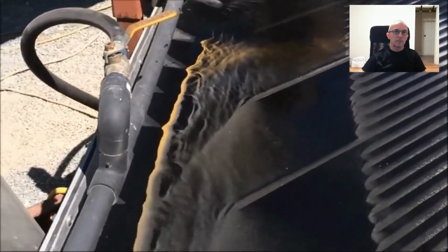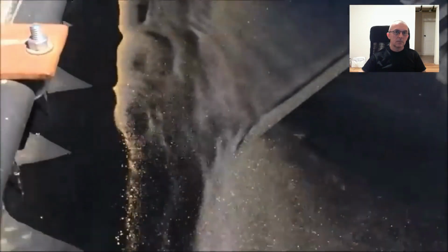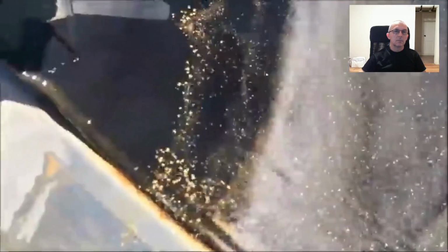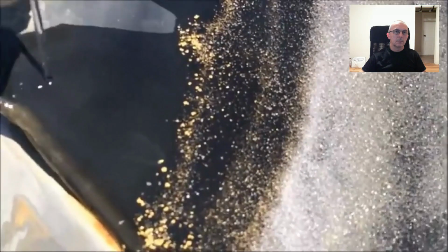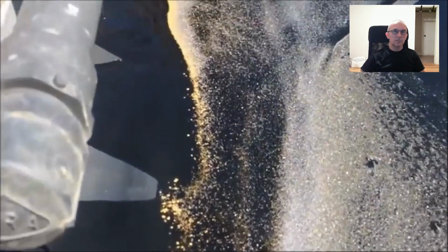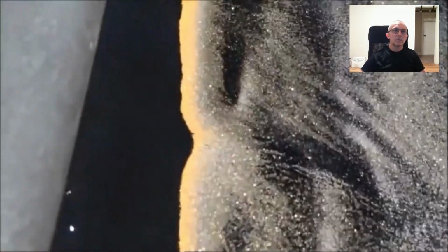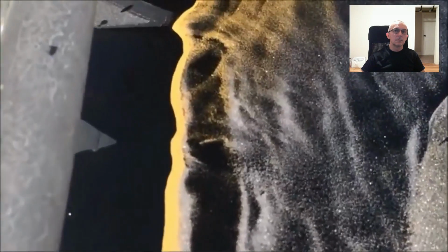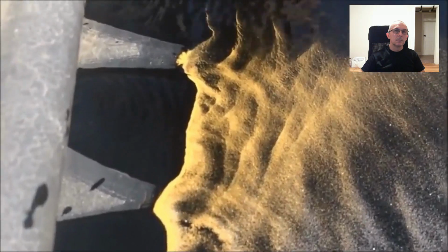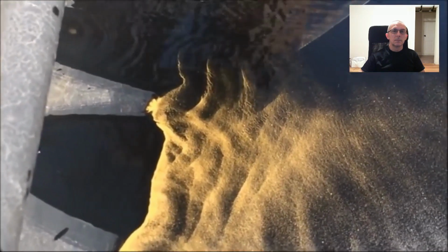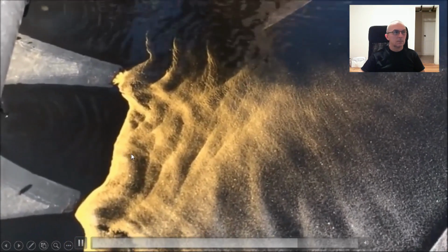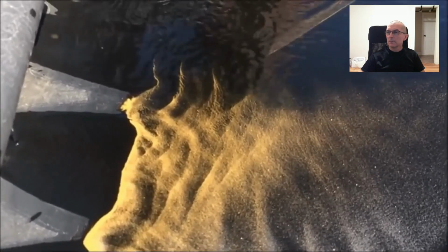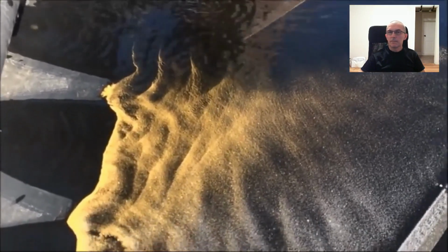The good part of this is just smoke on the table. The big pieces have come down already. They're already down here. These are the bigger pieces from the ore. And then on up here, this is actually fairly coarse here as well. And then we get up here, and this is just very fine smoke. Call it micron gold, call it flour gold. When we screen this, a good part of this will go through a 325 mesh screen.